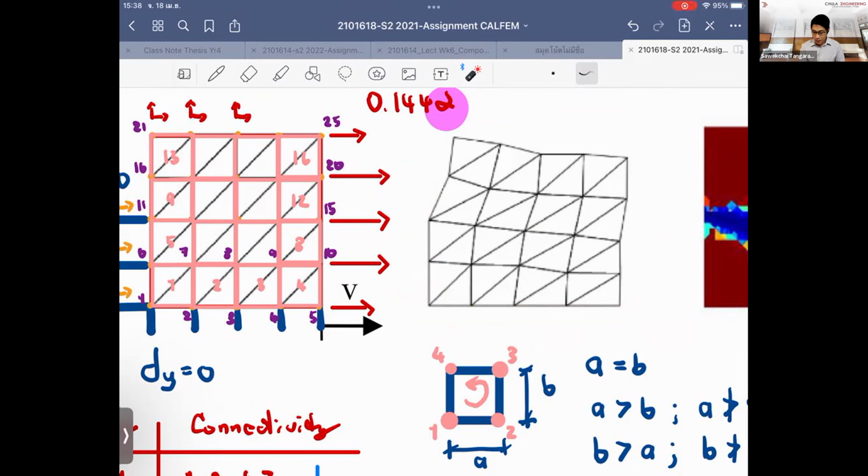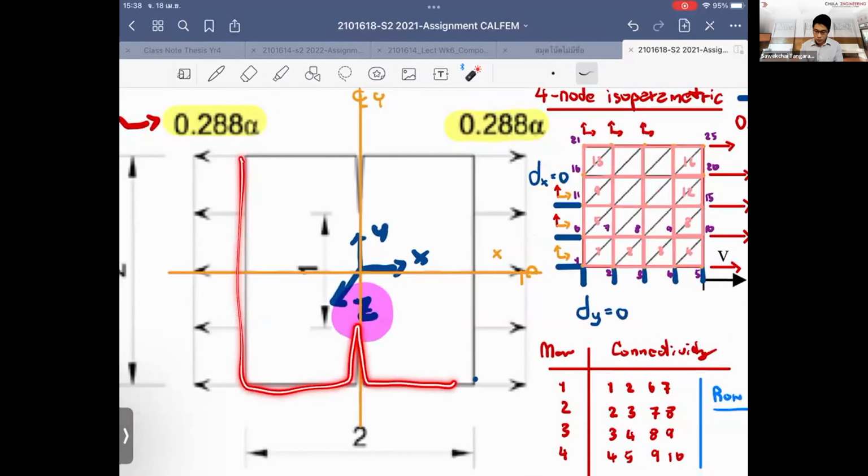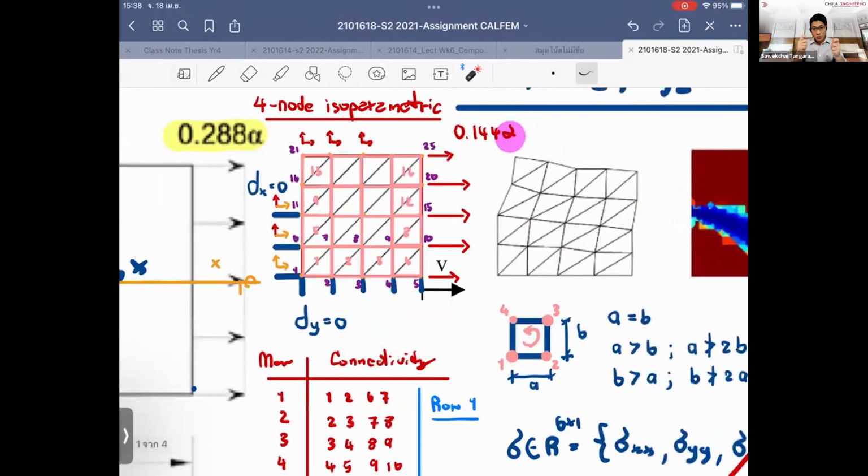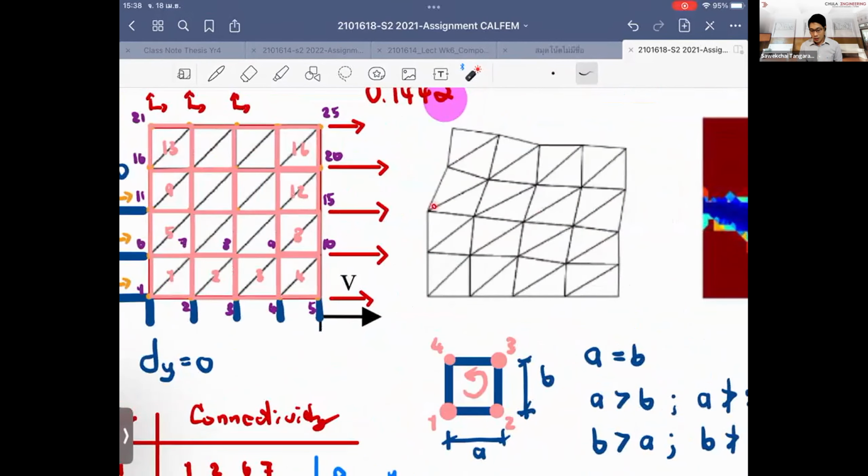If you have a thin sheet, you can try it with paper. Take a square piece of paper if you want to test for yourselves, and make a notch. Cut halfway across, and leave the remaining part bonded together. Then pull the paper slowly to the sides, so you apply tension. In the paper you experiment with, this is plane stress, and you will see that the more you pull the paper, the more it deforms like this. That tells the behavior of the thin sheet.